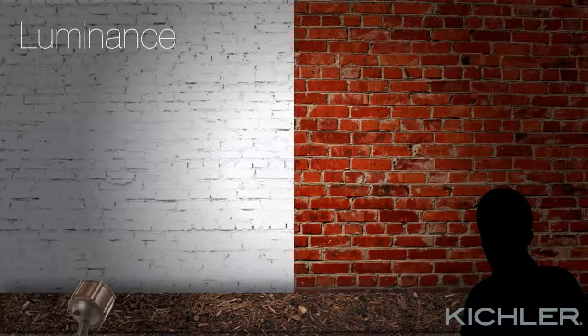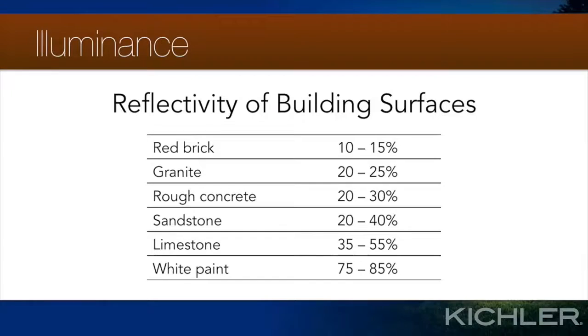That is, two surfaces with the same illuminance, the same number of foot candles of illumination, might have different luminance, a different number of candelas of luminance. If we look at the two kinds of brick in this image, we see that the white brick has greater luminance than the red brick. That is, it appears brighter, even though they receive equal amounts of light and shadow. What does this mean for your design? The thing to keep in mind is that lighter surfaces reflect more light than darker ones.